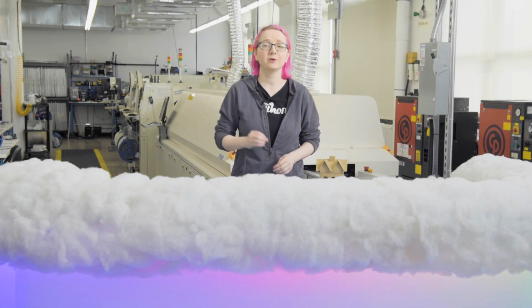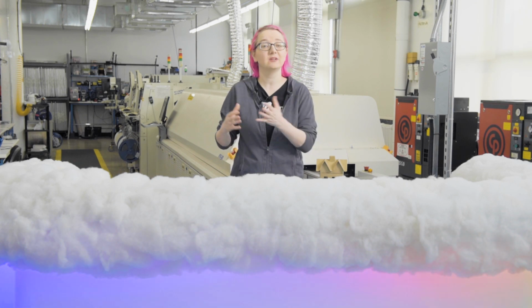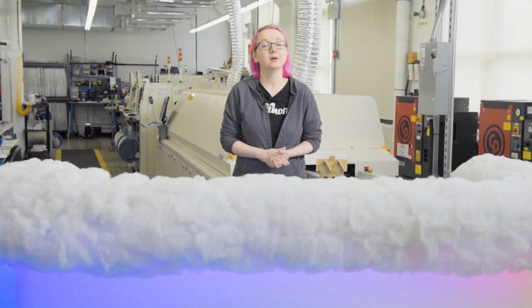Each transport has different power needs and bandwidth capabilities. Some are handy in that they connect directly to the internet. Some need gateways to access the internet, which can add cost and complexity. Transports directly affect your bill of materials and chipset selections, and it's very hard to adapt a product to use a new or different transport, and transports don't have a lot of overlap in their capabilities, so that's why it's the first thing to pick.